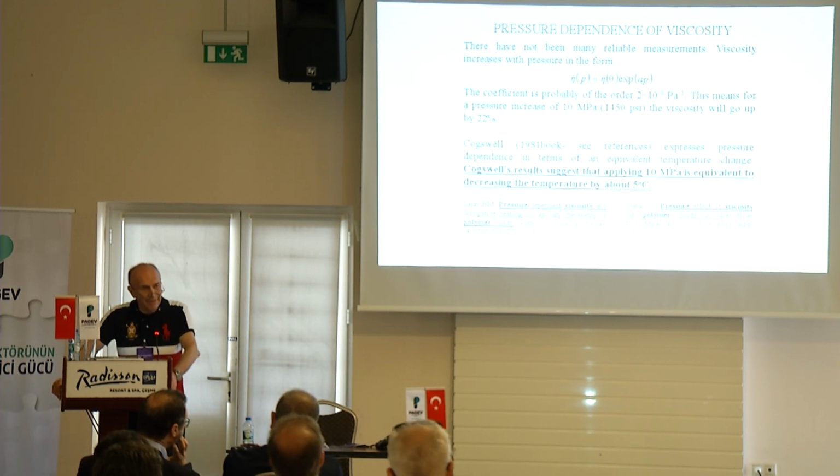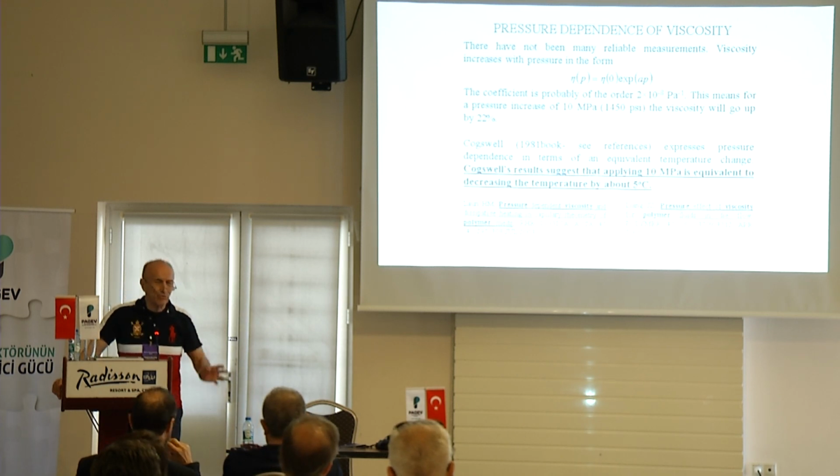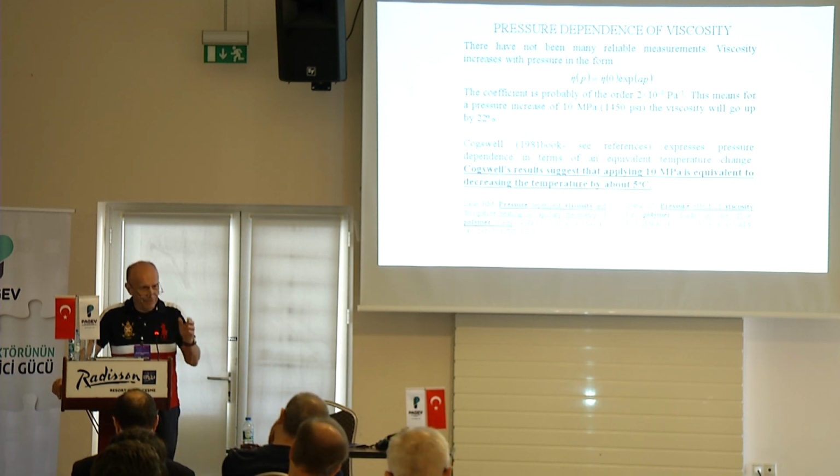It's a very high pressure. In extrusion, we can go perhaps up to 40, 50 megapascals, 500 bar or so. So in extrusion, we do not really use the dependence of viscosity on pressure in any calculations, but we do use it in injection molding.